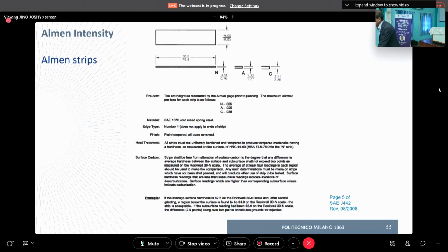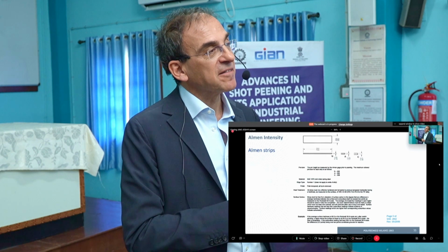Indeed. A is the most widely used. For common peened material and common peening conditions, A is the reference. But if we are peening, I don't know, magnesium alloy, for instance, or aluminum alloy, we could need a light intensity.